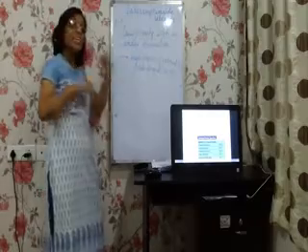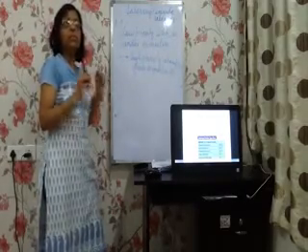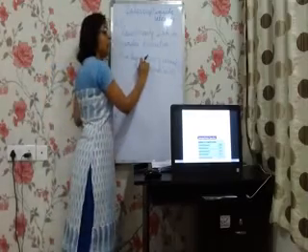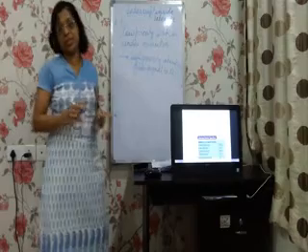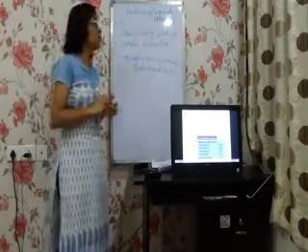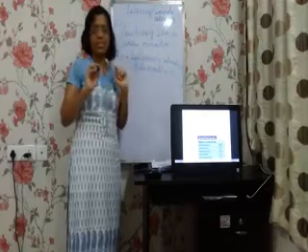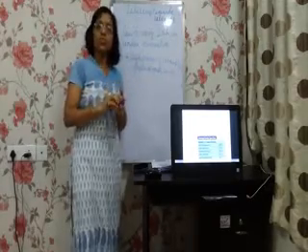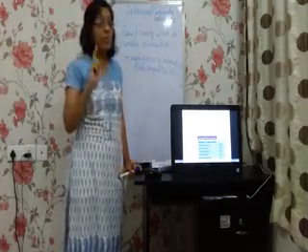So an interrupt is invoked inside an interrupt. This is possible if and only if a high priority interrupt request comes when a low priority ISR is being executed. Have you understood the concept of interrupt inside interrupt? This is called interrupt inside interrupt. With this we have finished the basics of interrupts, and we have done programming in assembly.